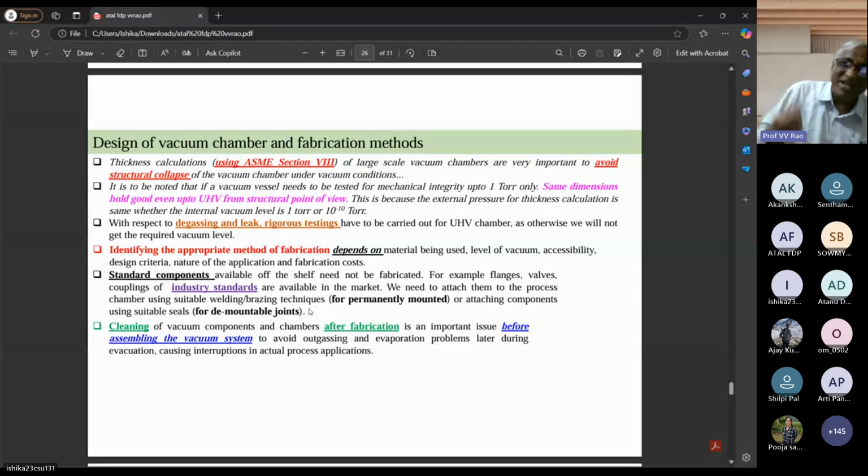So degassing is an intentional increased outgassing, but during that time, your process steps will be off. You should stop oxidation, stop impregnation, stop doping, everything. So actual things are all waiting. When the atmosphere is clean, only then will it come. So these fabrication methods, including cleaning of it, what type of cleaning agents you have to use for the fab, for the actual whatever is exposed to the vacuum, including the wafer on which you are forming, including the walls, the manipulators, the heating elements, walls, pins, feedthroughs, everything has to be degassable.